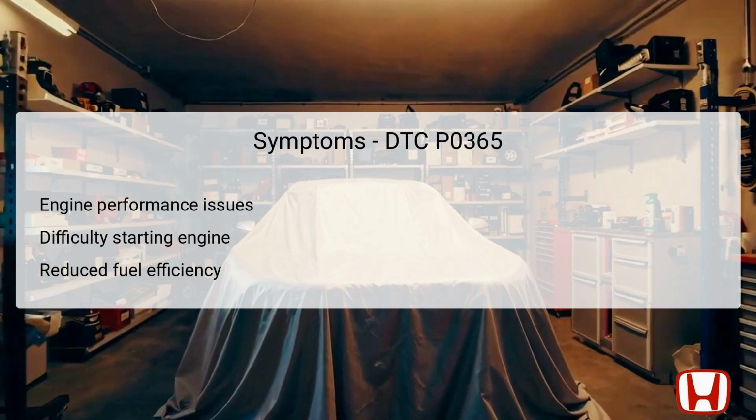Additionally, drivers may experience reduced fuel efficiency as the ECM struggles to optimize engine parameters without accurate input from the CMP sensor. These symptoms serve as crucial indicators of the need for immediate diagnostic work to resolve the issues tied to the CMP sensor circuit.